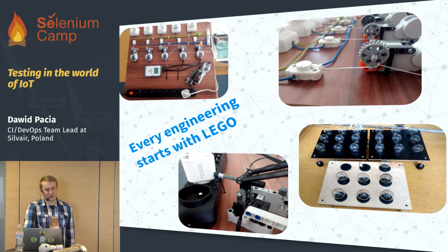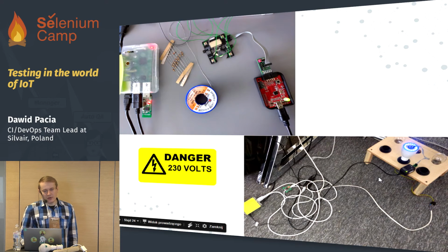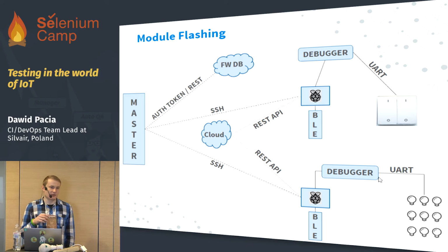And for me, that was a good lesson learned. But let's move to the challenges. And the first one: how to update firmware on the device to always be up to date. We used an embedded platform. Here is Raspberry Pi to gather the firmware from the cloud before it was built, and very often software was sent to the cloud, then downloaded and programmed by the debugger.